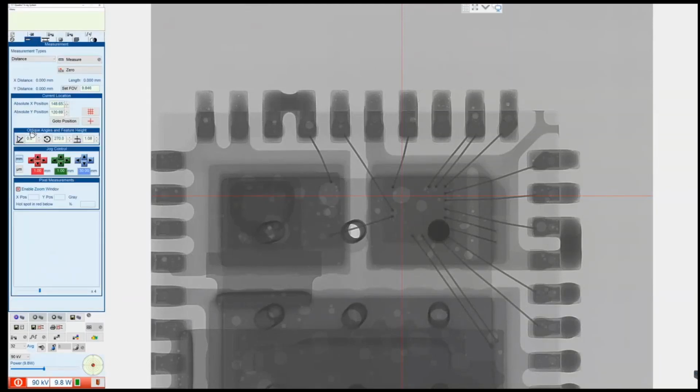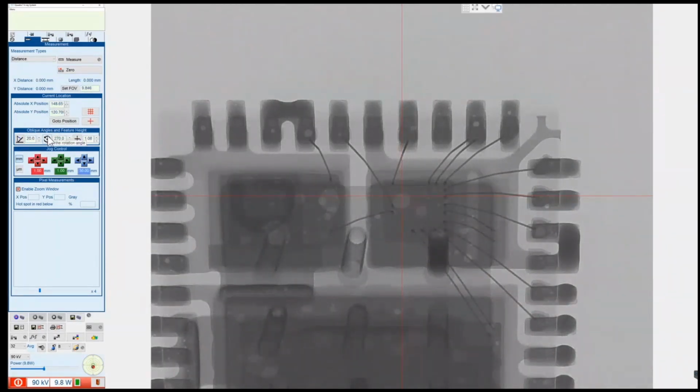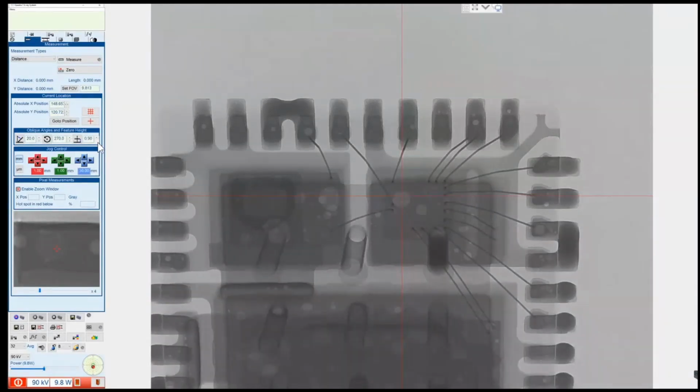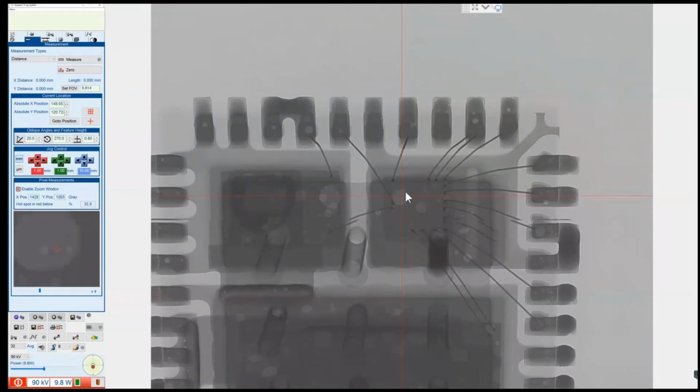So when I say low angle, I'm going to do 20 degrees. And what I'm checking here as the machine moves to a 20-degree angle is, has the center of my crosshair remained on the void that I want to use as a fiducial? So it's quite high up. I want to bring it towards the center. I'm just going to adjust this height value. Okay, and as I'm doing that, can you see that the center of the cross is now more toward the center of that void?